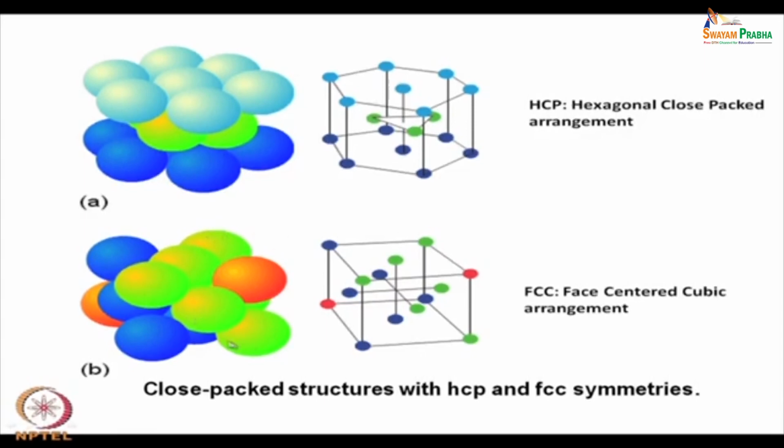The green ones are actually the close packed layer. So, it is a diagonal plane, and if you refer to this particular diagram of the cubic arrangement, you will see this diagonal, and then this diagonal connected to this corner. So, this diagonal plane is actually the close packed plane. There will be another diagonal plane from the blue ones. The blue ones form another diagonal plane. Okay. So, there are 2 parallel diagonal planes which are actually close packed planes, whereas the faces are not close packed.